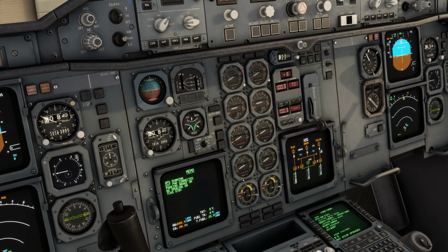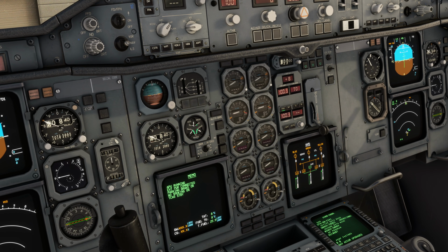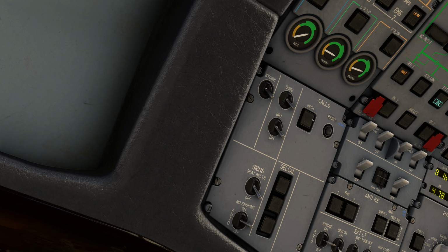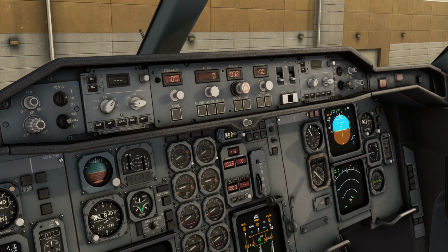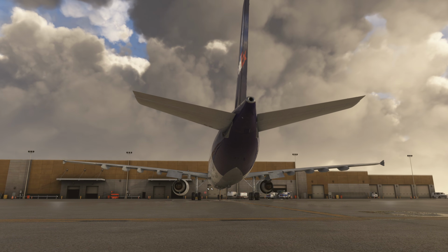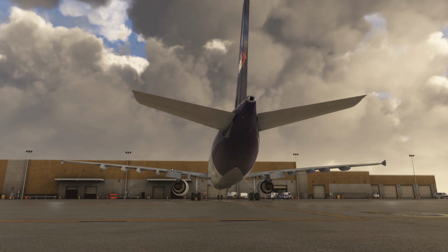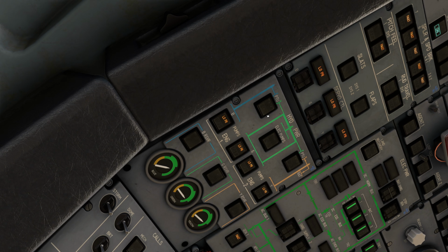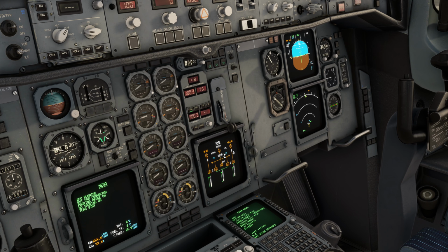In order to do that, and this is not mandatory unless the accu pressure is getting too low, but right now I would rather want to recharge this. So what we are going to do is, first of all, we're going to call the ground engineer and just talk to them to make sure that all the areas of the airplane are clear. So, for example, we are talking about things like nobody standing close to the gear doors or to any control surface over here. And when we are sure that everything is clear outside, then we can go to the hydraulic panel, turn on the electric pump that is going to pressurize the green system, as we can see down here.